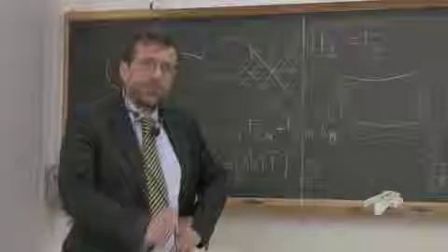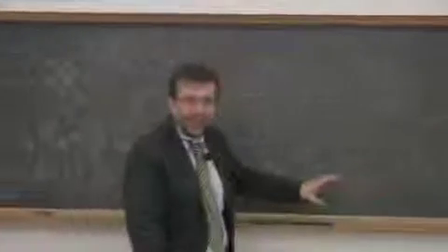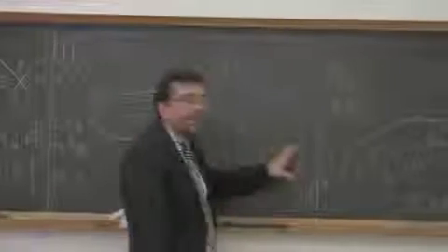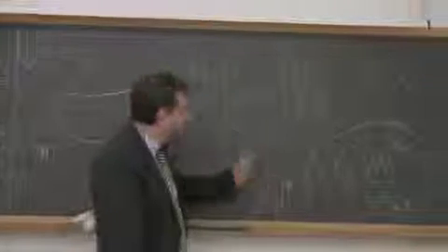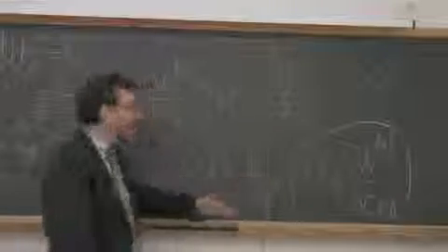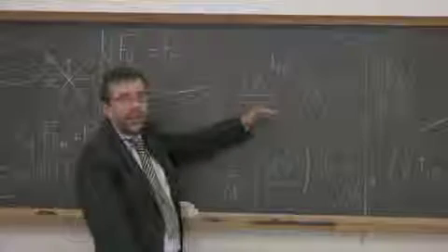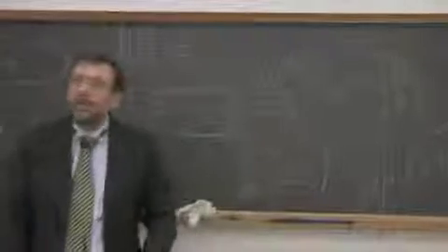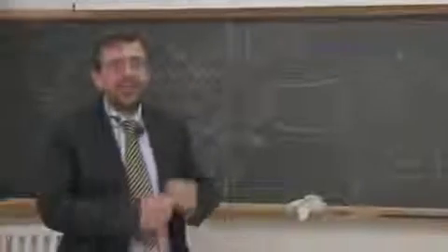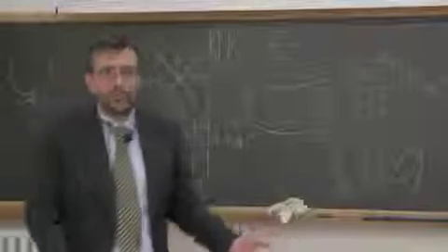This is the reason for which we will do the next step. We will solve Piola's problem: how to transport this equation from Lagrangian description into Eulerian one. So we will be able to use the description which is more suitable when it is more suitable.